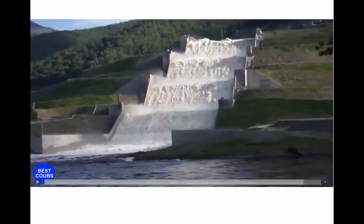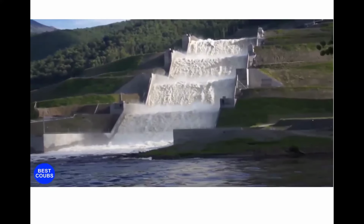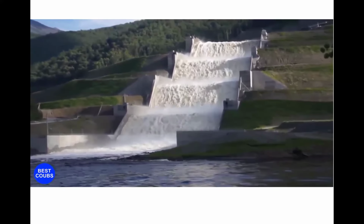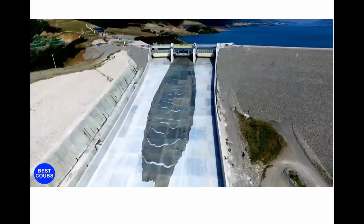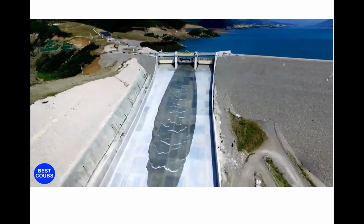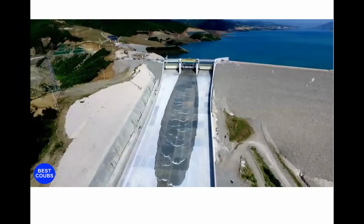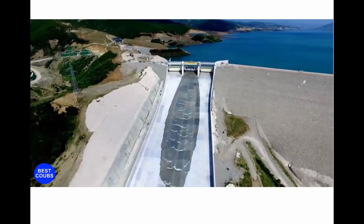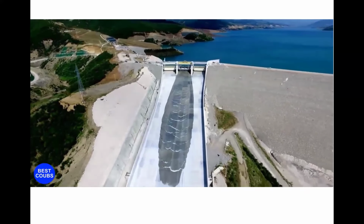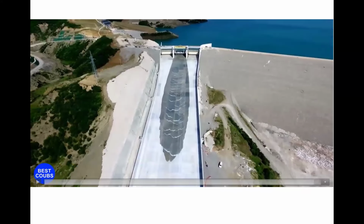Another discharge structure. This one's an interesting one. This is almost a stepped spillway. So this is again relatively common. Instead of having one chute with one smooth surface, you have a bunch of steps, and each step basically drops lower down and dissipates a little bit of energy, and you keep doing that on a bunch of steps until we reach the bottom of the spillway.